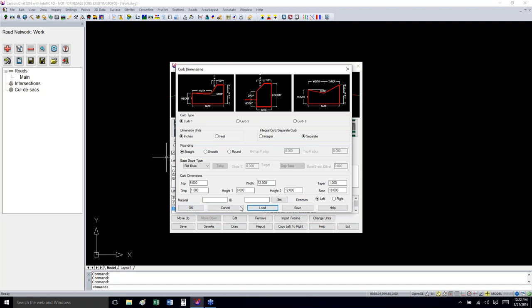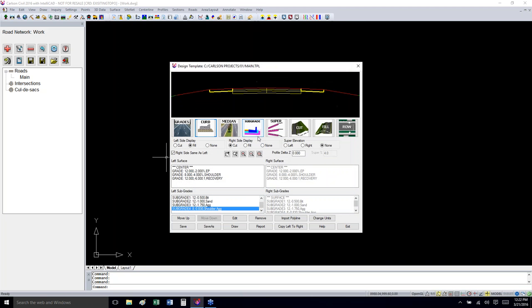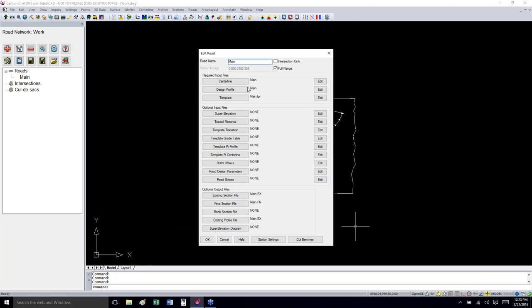We also do a fine job at medians. So anything you want to build a template for, we can handle. So let's save this and exit. Now we have our 3 required. There's really 4 required: you need that existing surface. So remember the 4th one. By the way, if I hadn't picked it in options, it would have come up and said you don't have an existing surface, and you can just choose it there.